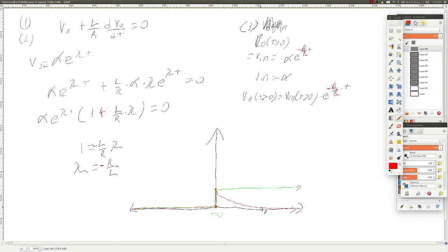So over time, an inductor is going to look like a short, and a capacitor is going to look like an open circuit. So if an inductor is charging towards being a short, then it makes sense that after a long time, the inductor's current will be limited by the resistor in this circuit. This means that over time, there will be no voltage gap across the inductor. So it makes sense that over time, the inductor is going to charge so that there's 0 volts across it.